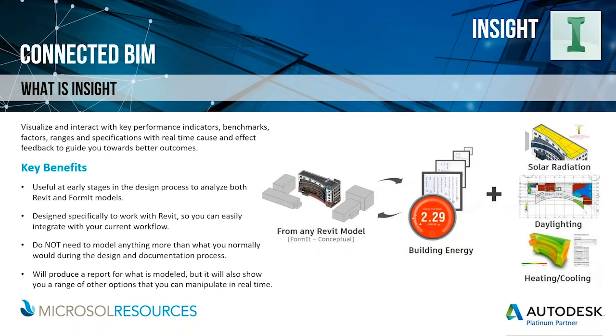For both FormIt and Revit design environments, the only required setting is the location. This is because Insight will run the range of outcomes for you, so while you can get yourself versed in the advanced settings, you certainly don't need to worry about that. And again, the goal here is to review the tip of the iceberg for some of these tools so that you don't feel like you have to become a master at any one of them.